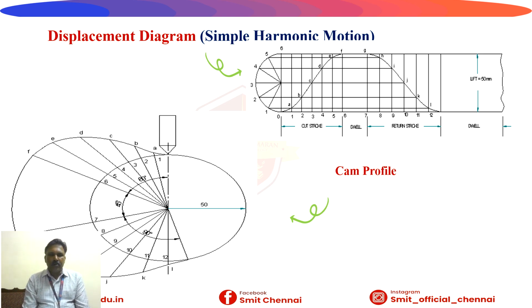Then what you have to do in this? You have to divide that angle into 6 equal parts. We should not divide the dwell area into various parts. There is no need to divide the dwell area. Only we have to divide the outstroke and the return stroke. The first angle, we divide into 6 equal parts. Then we have to divide the 90 also into 6 equal parts.